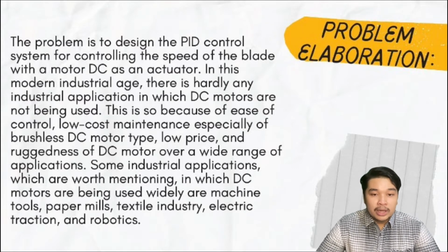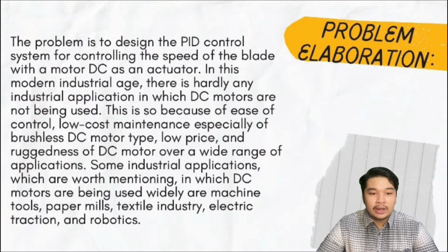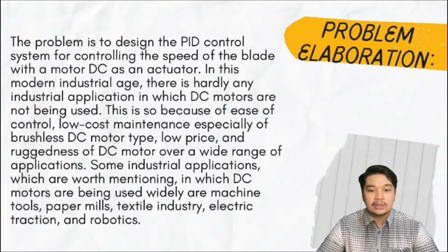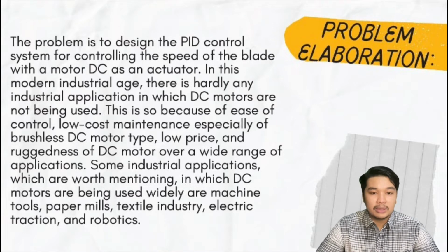For tuning a PID controller through these techniques, expertise and experience are required. This is because these methods provide a starting point for achieving desired performance. Fine-tuning of parameters through the hit and trial method is required. However, meta-heuristic techniques may be a good choice due to their dynamic nature.